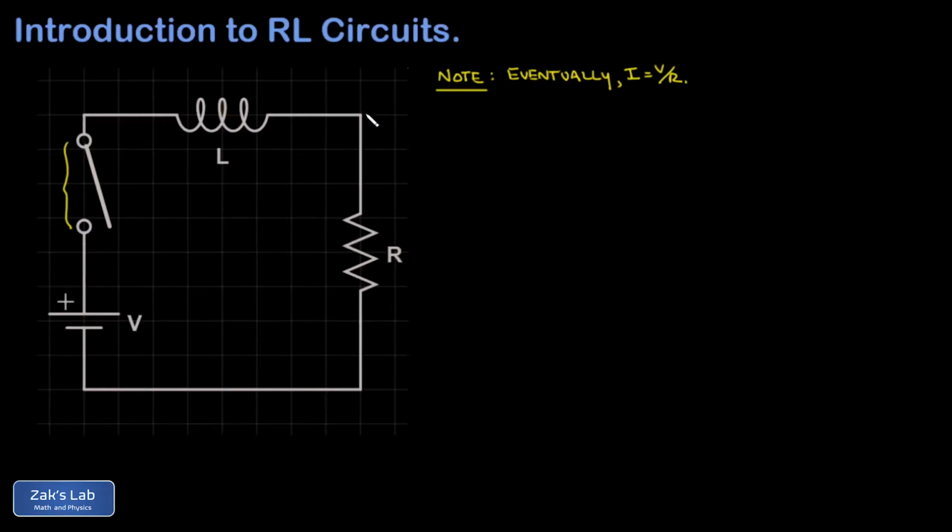across the resistor. So I'm going to label a couple nodes in the circuit, one above the resistor and one below the resistor that's actually connected to ground. Well, the voltage across that resistor is the combination of my positive voltage from the power source and the back EMF induced in that inductor. That inductor is attempting to reduce the current in the circuit, so it's going to produce a negative voltage and reduce the total voltage across that resistor compared to just the power source itself.